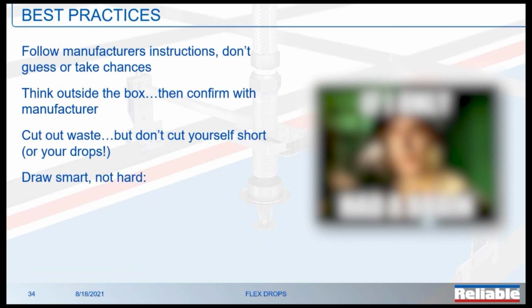And then finally, just a couple things here that I always like to keep in mind. Draw smart, not hard. Keep the fitter working in a straight line. This is maybe for some younger designers, things to keep in mind. Keep your fitter moving in a straight line. He's going to be much more efficient that way. Don't have him go side to side. Think about which offset makes more sense from a cost standpoint.